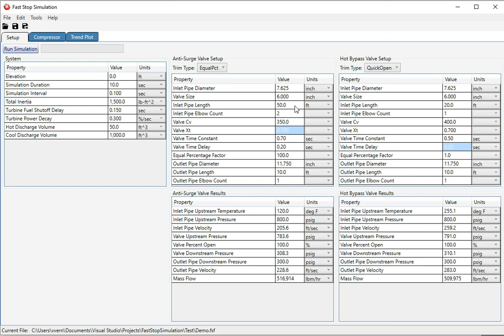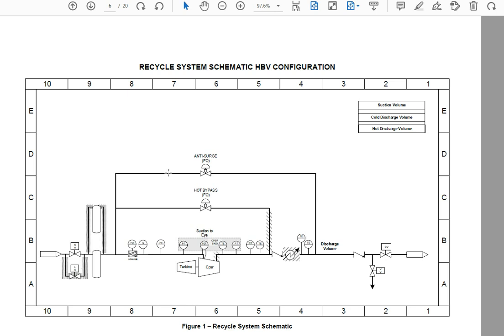This is a trick to model the pressure drop across this combination of pipes and a valve. You need to solve for the intermediate pressures upstream and downstream of the valve. So it's an iterative solution, iterating on flow rate, solving for pressures through the system, and keeping at it until you converge on equal flow in this section of pipe, the valve, and the downstream pipe. So I'm iterating on these two pressures, upstream and downstream of the valve.